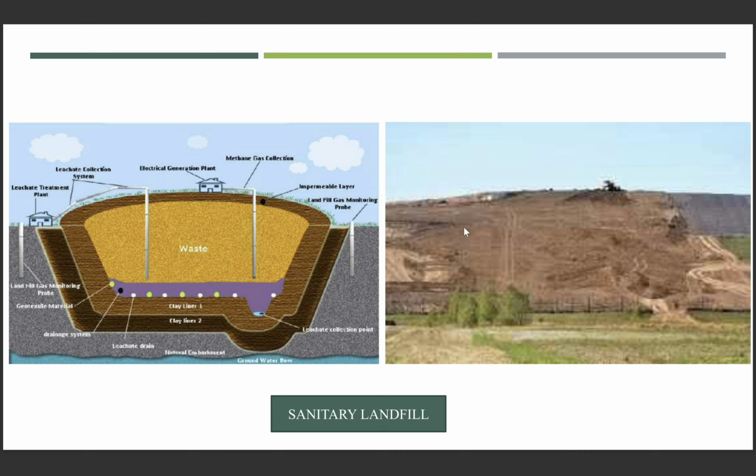Next, the waste is put into cells, and each cell is covered at the end of the day using nearby soil. So the waste is not open to animals and pathogens. That's why they will not create a nuisance, and birds and animals will not be attracted towards it.